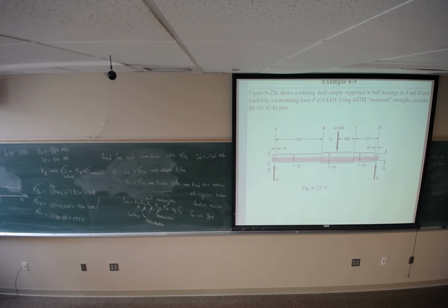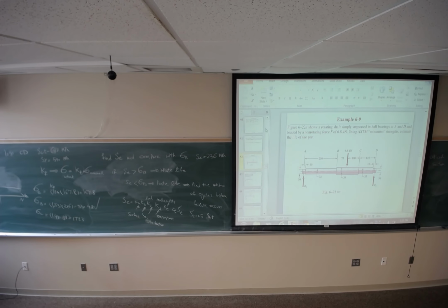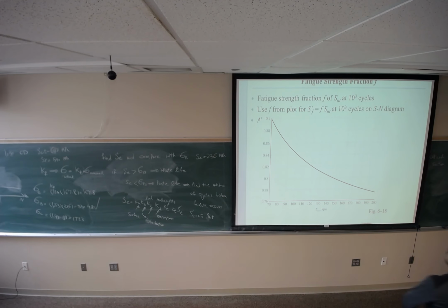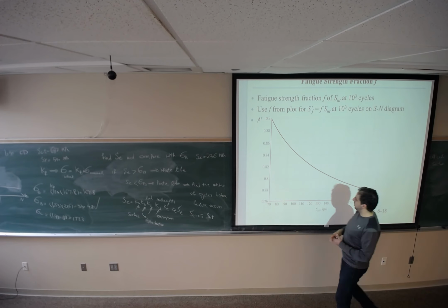Figure 6-18 gives the fatigue strength factor f, depending on the S ultimate, so you can read the value of f.